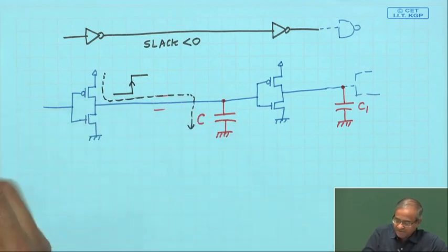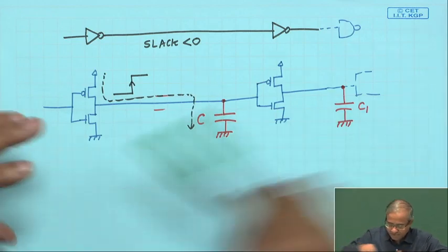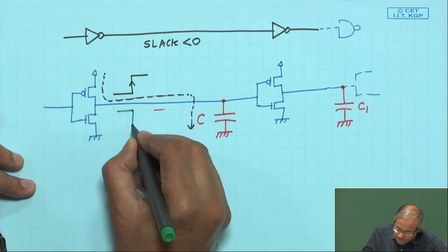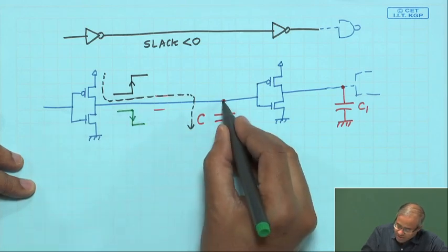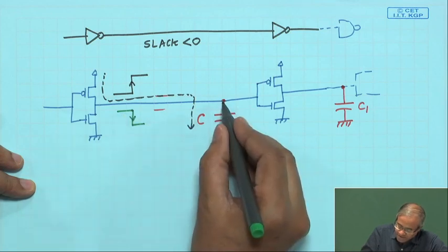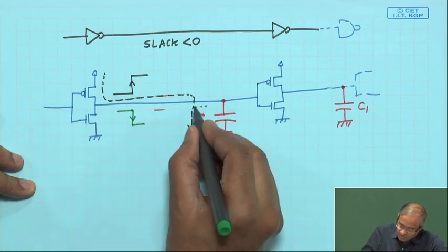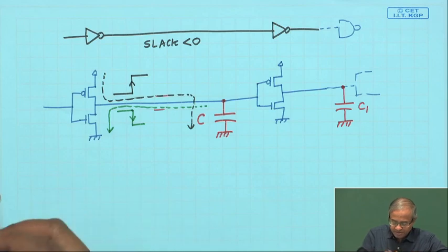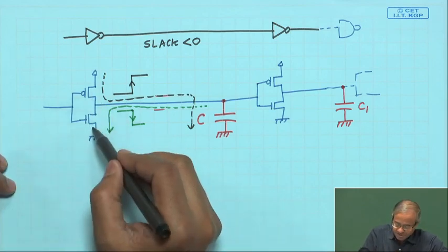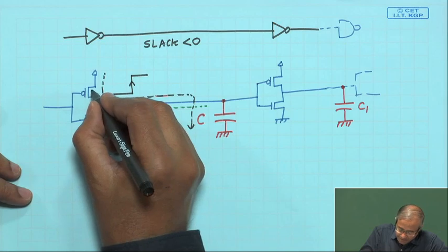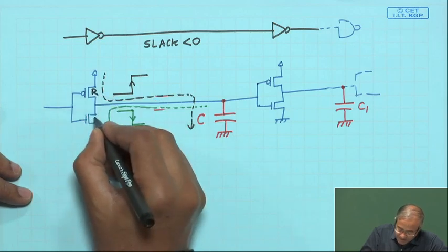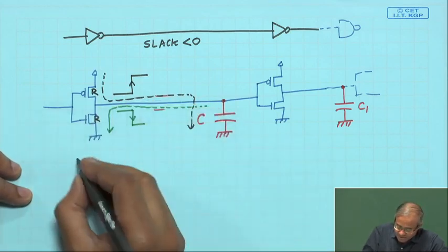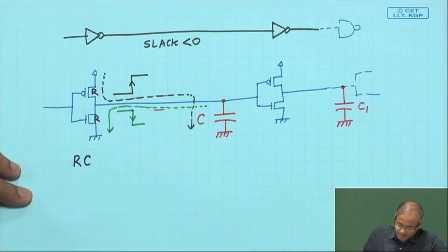So, this p type transistor is coming into the picture, and similarly when I say that the output of this gate is going from 1 to 0, which means the capacitor was already in the charge state, it is 1, high, it is discharging through this path. So, now the discharging path will be like this. So, either the PMOS transistor or the NMOS transistor will be conducting. If I just assume for the sake of argument that the resistances of these two transistors in the conducting state are equal, the charge discharging delay will be RC, the product of that.